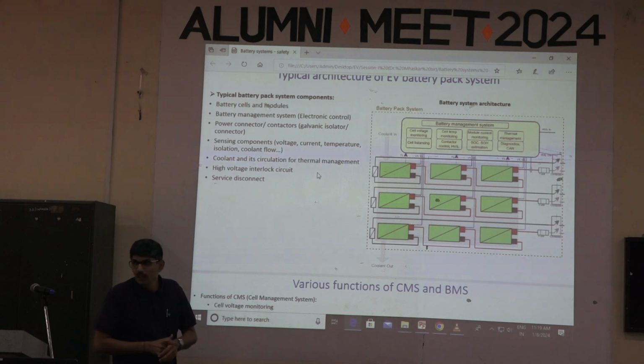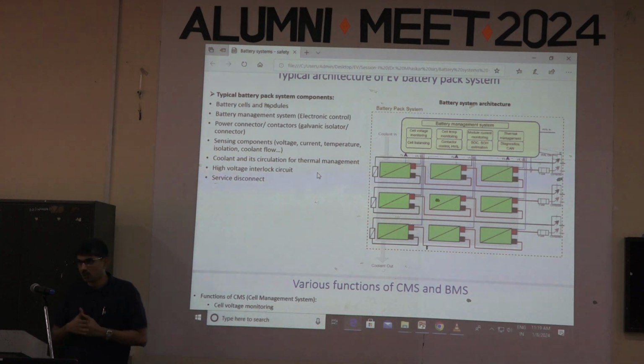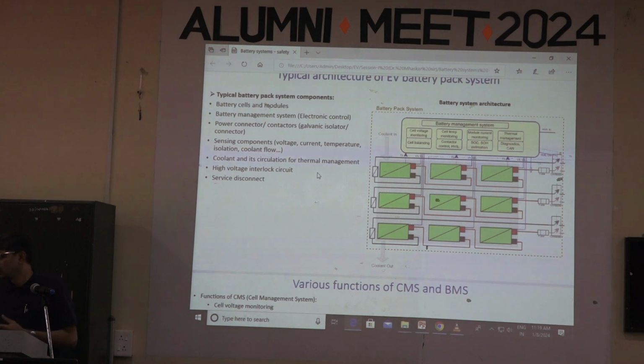Then diagnostic and CAN, because if CAN is broken or the wired communication is broken, then we literally halt the vehicle on the ground. We don't allow the vehicle to move forward or even backward, not even by an inch in both directions. The reason is naturally safety.